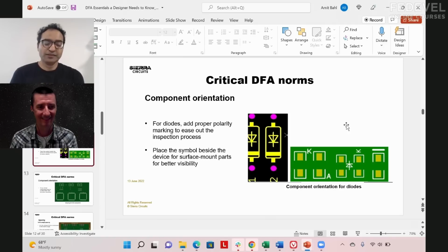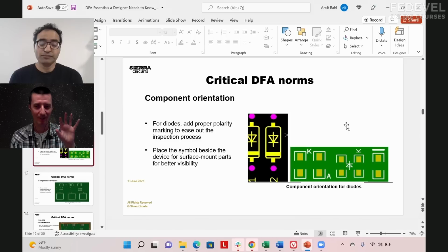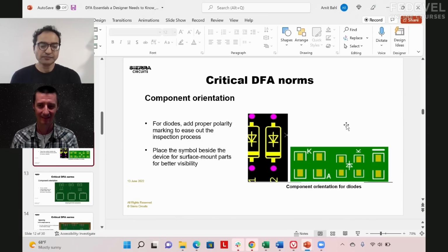Understand where your pin one is on the component and understand that your marking is there and correct. So what do you usually see when you say it's the most common mistake? Is there a difference between component rotation in the pick and place file compared to the footprint? Yeah, that's exactly the issue.